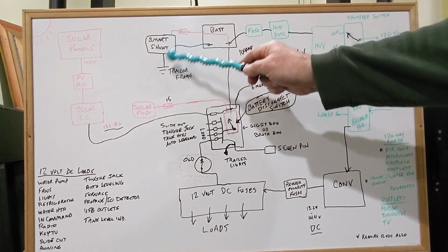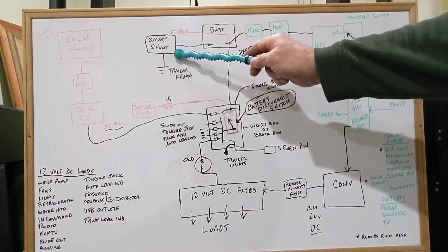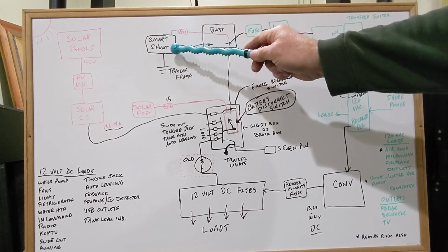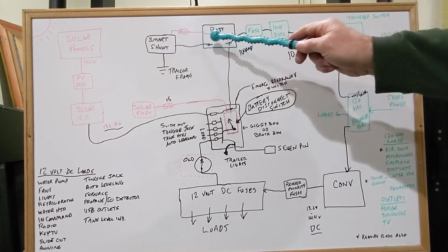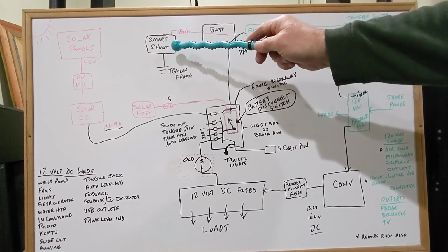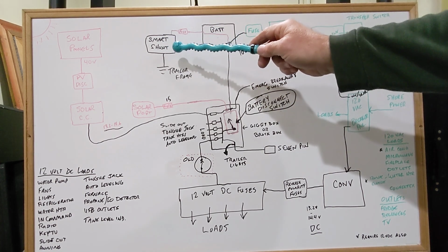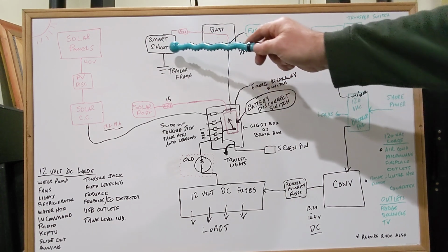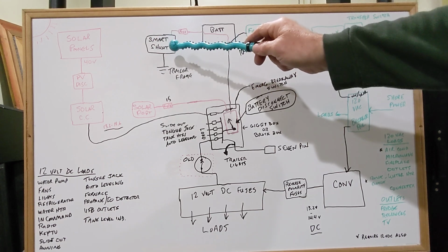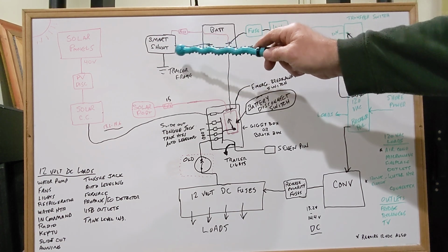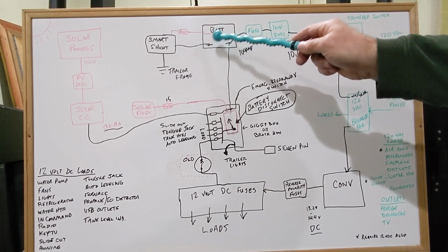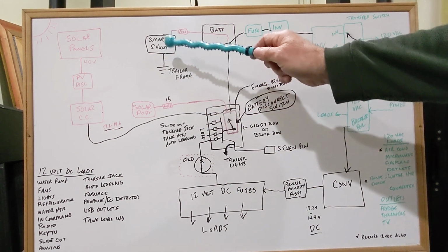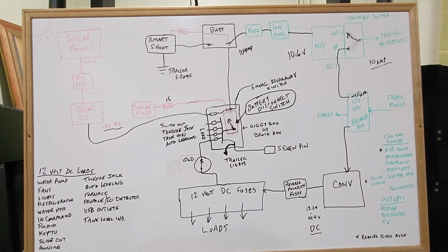Same thing with the smart shunt as a solar controller. Your Victron Connect app, you can Bluetooth connect to the smart shunt, and you have to set the battery settings up properly to match what kind of battery you have, so the smart shunt knows how to do the calculations properly to tell you what the state of charge is. So if you haven't set the battery settings up, the state of charge on that is worthless, because it doesn't know what kind of battery you have and everything. So very important, you got to go in there and make sure your settings are correct.